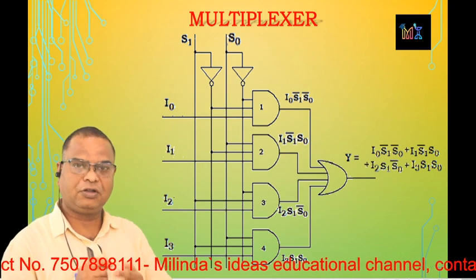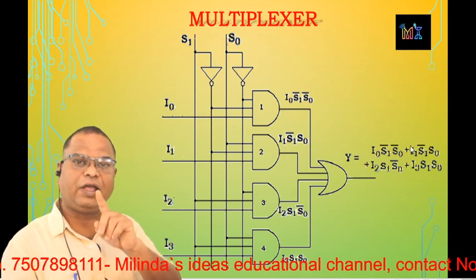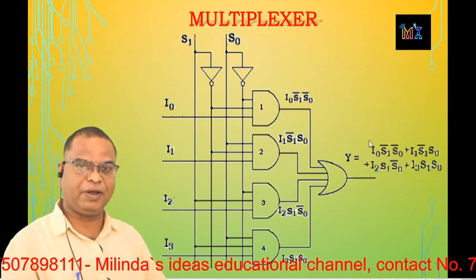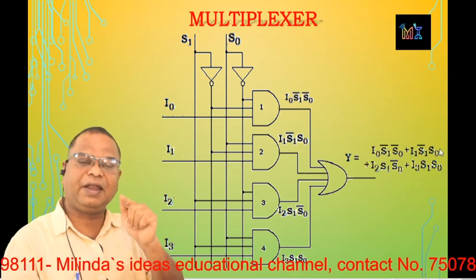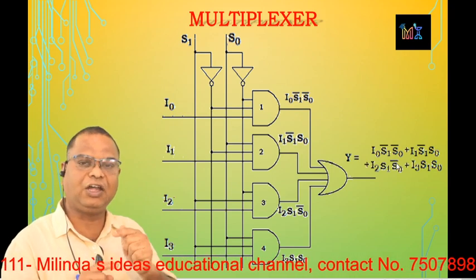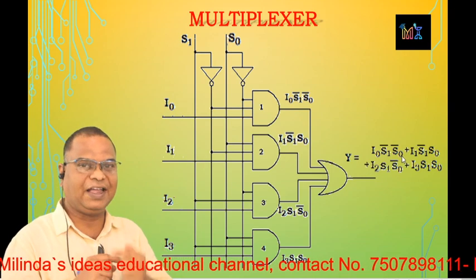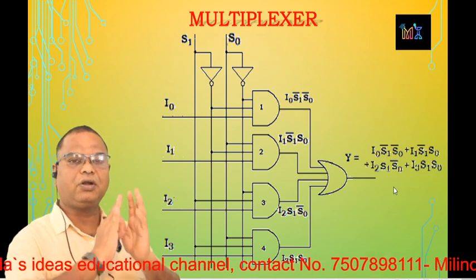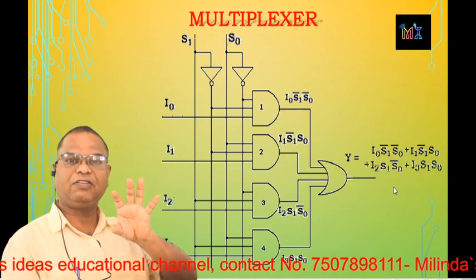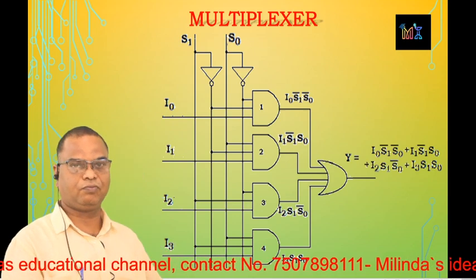Let us repeat. The output of the OR gate is Y is equal to I0, S1 complement, S0 complement, plus I1, S1 complement, S0, plus I2, S1, S0 complement, plus I3, S1, S0, and that is the output of our multiplexer. So that is the circuit diagram, that is the logic diagram of the 4:1 mux.